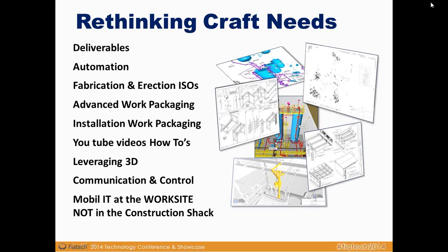We're not leveraging 3D to the advantage. Matter of fact, I just interviewed a construction manager last week. He said that the 3D model, that most people use, is next to worthless in the field. It kind of sort of shows you what it's going to look like, but it doesn't do the craftsman any value at all. And he says, to make it worse, since they gave us a 3D model, that's back up in the construction shack, by the way, they decided we didn't need plans and sections, so they throw about 2,000 ISOs at us. And we've got to figure out where these ISOs are in space and then how to erect them and fabricate them. The model does not show field welds.